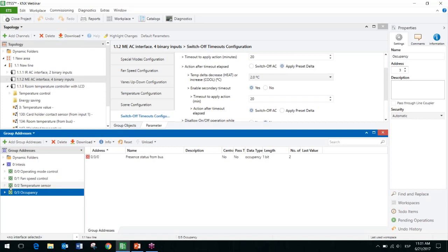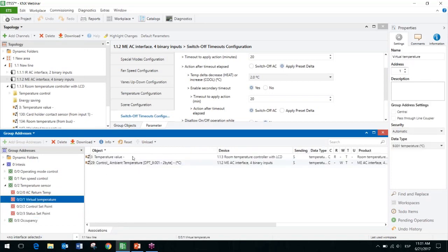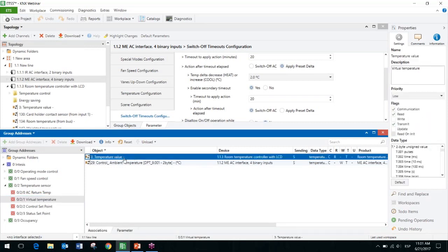So what I only did is create a group address and then link together, for example, the temperature value coming from the KNX thermostat, which is this object, okay? And I link it with the control object of my gateway. In this way, by putting them together in the same group address, I can be sure that they will be communicating to each other. So I don't know if I answered your question or...